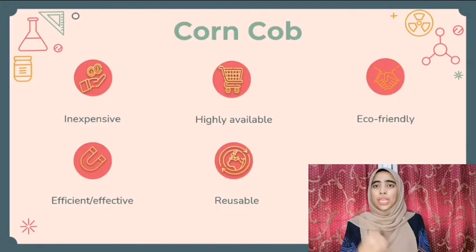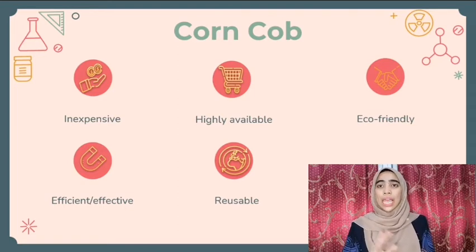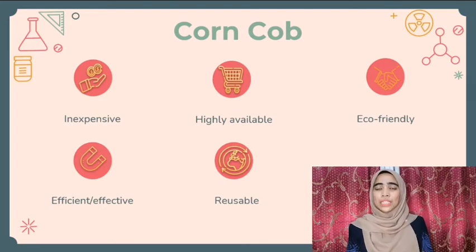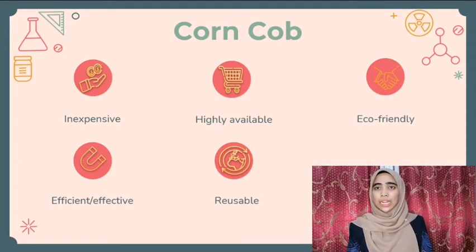Recent studies use mango peels, almond peels, rice husks, sugarcane bagasse, and also corn cob. In this study, corn cob is used as bioabsorbent due to its ability, low cost, eco-friendliness, and being a reusable raw material. Corn cob is a biomass feedstock with the ability to absorb heavy metals in wastewater or industrial effluent. Anthony et al. 2017 state that corn cob has 5.1% moisture content, 8.5% ash content, 44.4% carbon, 5.6% hydrogen, and 48.27% oxygen.